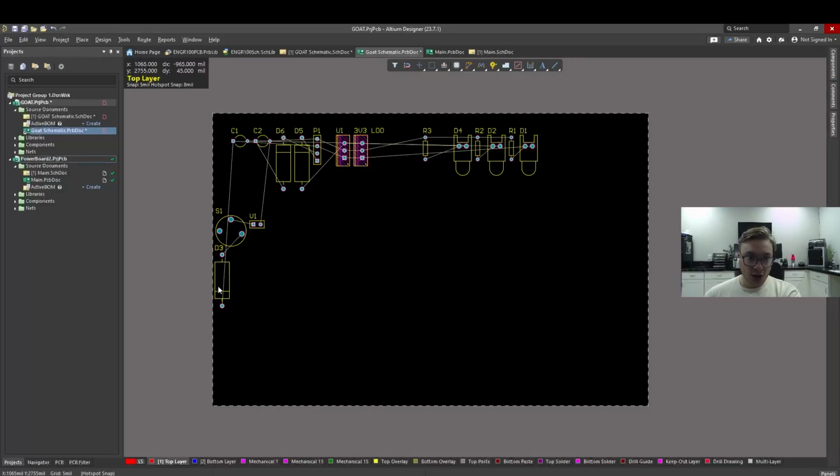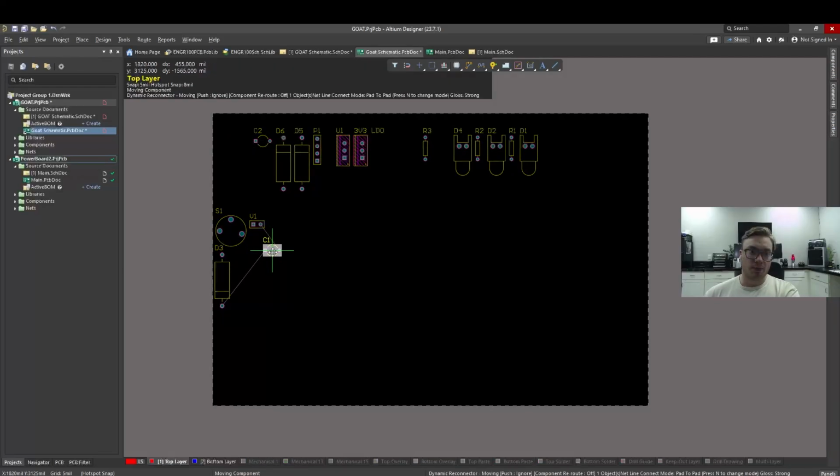So here's our battery protection diode. And you'll notice those designators that we assigned previously, those actually follow these parts, and you can actually print those onto your circuit board. So anything in yellow is going to be ink printed onto the surface of the circuit board. So that allows us to know what parts go where, basically. So here's our decoupling capacitor for the input, right?